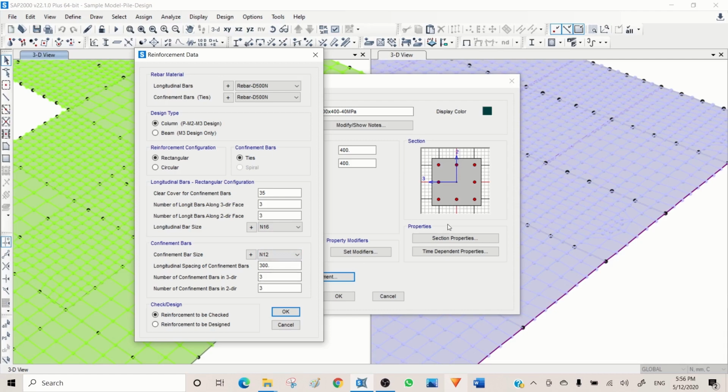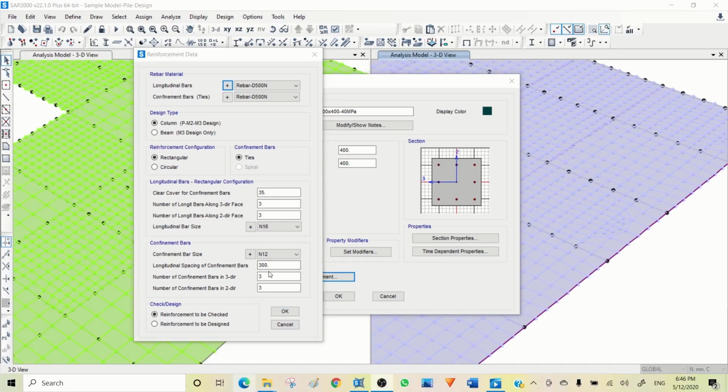Currently, all I'm doing is calculating the shear capacity of the column. I just want to ensure that this space with this arrangement of bar is sufficient to support the shear load. Then for confinement and ductility requirement, if I need to add more rebar, I will. So the whole purpose of preparing this arrangement is just checking the shear capacity.